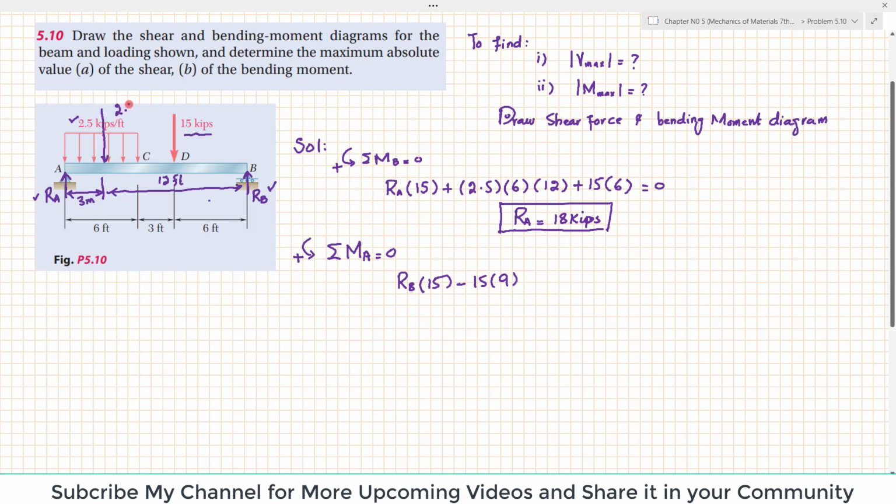So 2.5 times 6 will be the concentrated load, and the perpendicular distance is 3. This is producing clockwise moment, so it will be negative. Their sum must be equal to 0. When you calculate it, you will get RB equal to 12 kips.